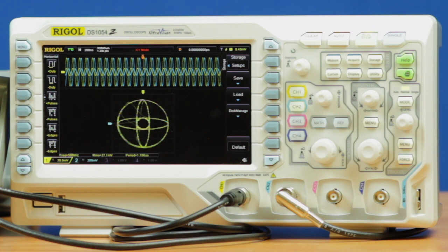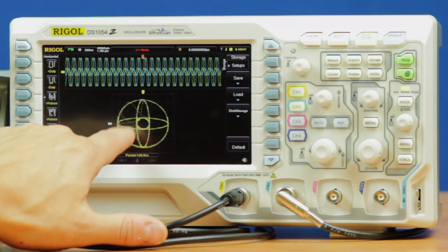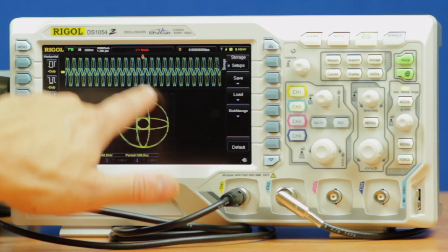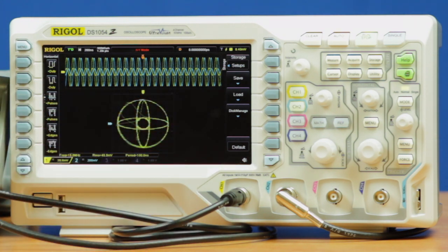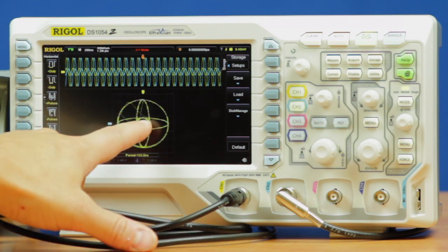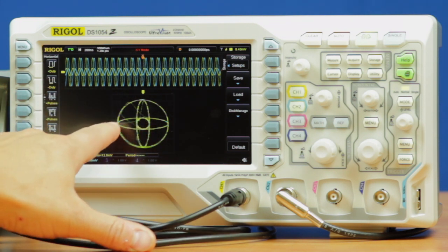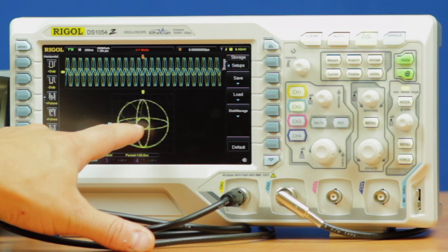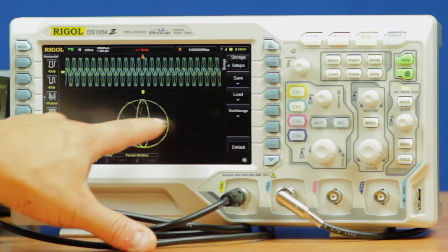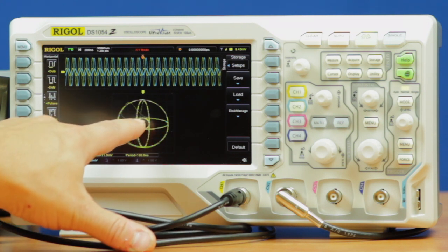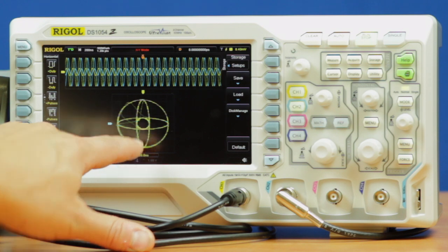What's also happening is you can see the two levels of amplitude here. The inside circle being a lower amplitude, the outside circle being a higher amplitude. Another way to verify that these signals are 90 degrees out of phase is if we look down the center line of channel 1, we can see that when channel 1 is 0, channel 2 is always very high or low. When channel 2 is 0, channel 1 is high or low.